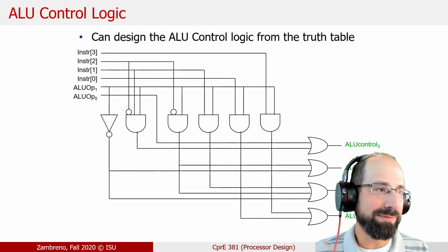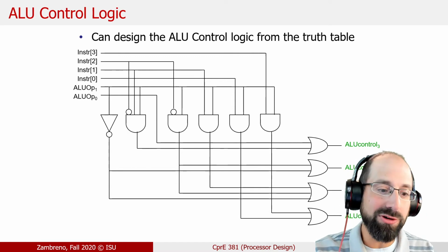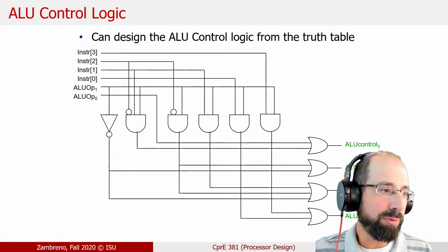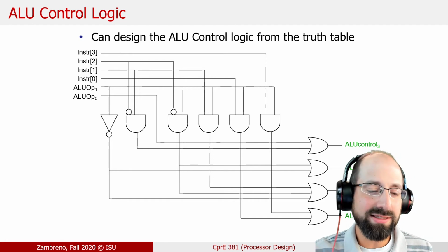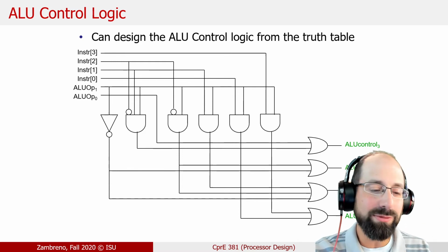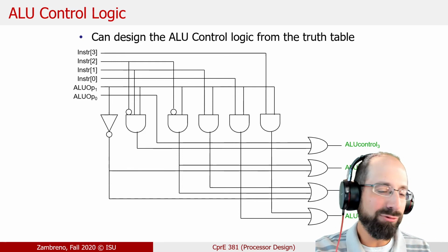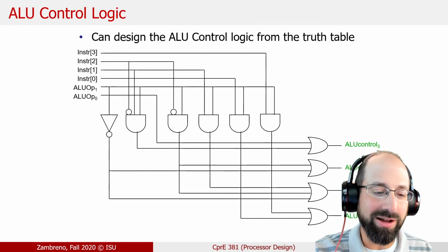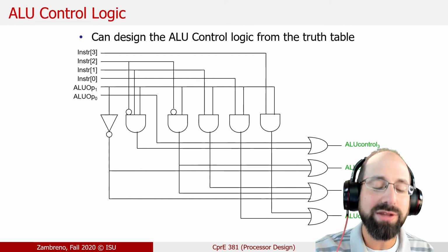That seems really unnecessary to me. And so our approach is don't really try to optimize at all. If you and your partner can't agree if it should be one signal or two control signals, well, make it two control signals. And even if one of them is technically redundant, it's okay. The synthesis tools will be able to detect that and eliminate the one in your actual underlying FPGA